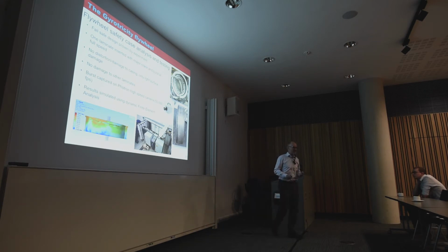There were lots of sparks. We had a plastic lid and filmed it with the camera. It didn't even break through the plastic. So it was an amazingly benign failure mode, and that's what's good, because I don't want something that isn't contained in the casing. We simulated this to death with finite elements, and we've got a nice high-speed camera that does up to 2 million frames a second. It was all good fun, and everyone was holding their breath. There was this almighty bang, and we're going to be doing that again on a much bigger one. That's the next challenge.